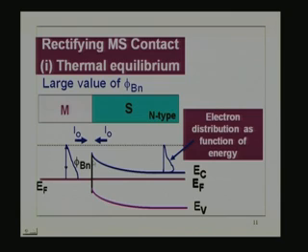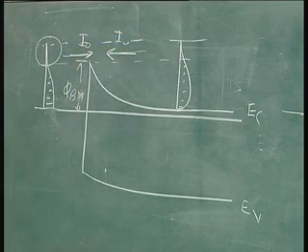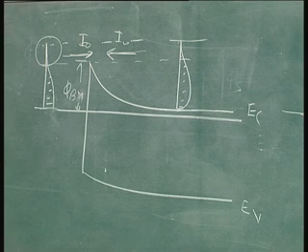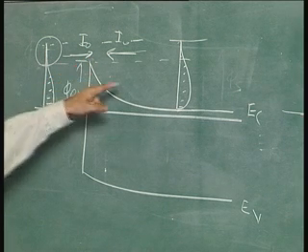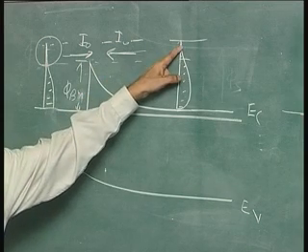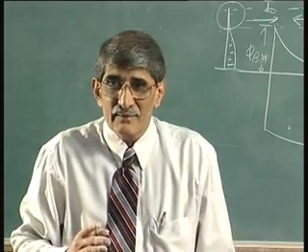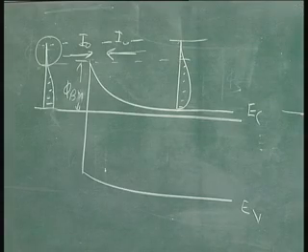Okay. Now, what I have put here is I naught. What is that I naught? If you understand this, we can quickly go through the whole thing. This quantity gives rise to the current I naught here, and this quantity gives rise to current I naught here. That is what I have marked. All those electrons which have energy above this barrier, that portion on the left hand side that I have circled here, will be crossing this barrier. There is no barrier, that will give rise to current I naught. These electrons which have energy above that give rise to current I naught to compensate. In other words, the net flow of electrons is 0, I naught from there, I naught from here. If you disturb that, you will be disturbing the current injected from the left hand side and right hand side. Okay? So, this is the situation in thermal equilibrium conditions.